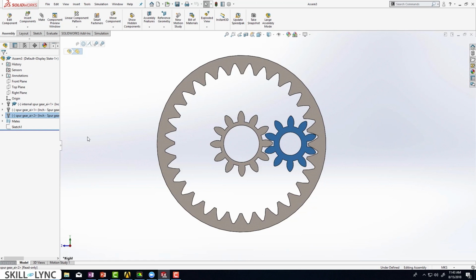That's basically it. Similarly, you have something called the diameter pitch. The diameter pitch is nothing but the inverse of module. If you are using the metric system, then typically we use a module specification. If it's inch based, then you go for diameter pitch. Now, in order for the two gears to mate correctly and transfer power correctly, the pitch circles of both the gears should be tangent to each other. And in addition to this, the module should be the same for the two gears.